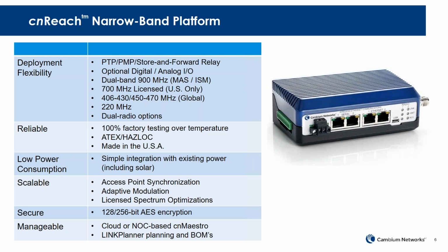The product has an optional general purpose I/O that you can build into the product, so that's an optional feature, but it provides digital or analog inputs and outputs directly on the radio. And in some cases, that can eliminate the need for an external RTU or PLC and allow you to do some simple things like, I just want to monitor door opening and closing. Maybe I want to monitor a couple of pressures. I want to keep track of a particular location.